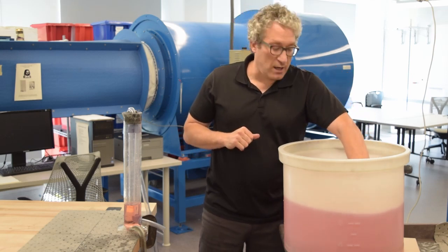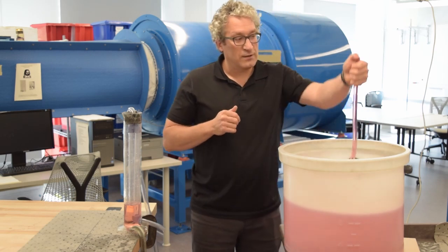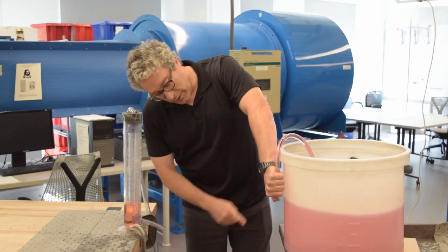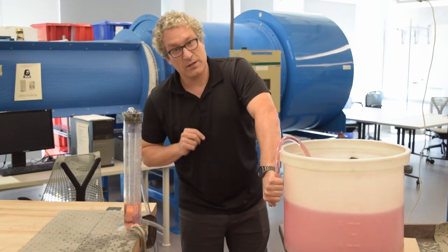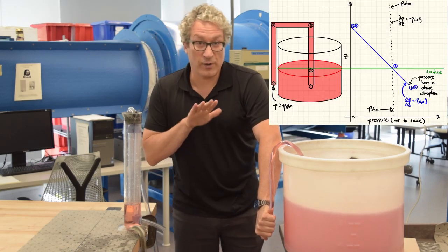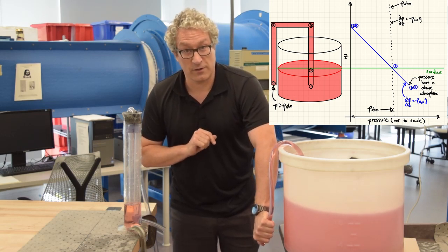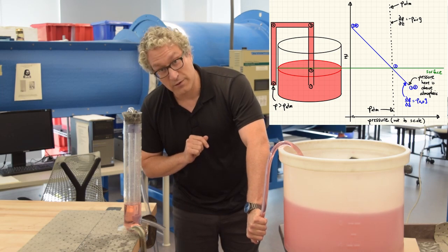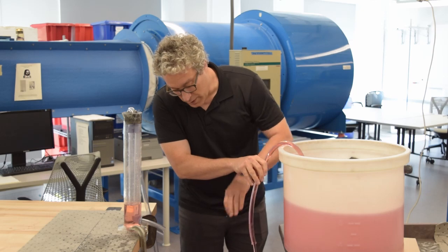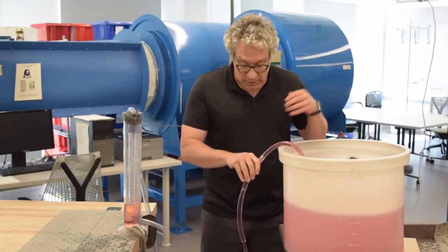But I can do the same math, and I can see what the hydrostatic equation tells me. And what it tells me is that if I hold it like this, the pressure here is lower. If I move it down and down, if I move the surface of this right even with the top, then I expect this pressure to be atmospheric. But as soon as I move this system down lower, now it has a lower z value, which means that the pressure of the fluid must be higher than that of atmospheric. And that means that when I remove my thumb, the water is going to come out. And this tube in this configuration, all it's doing is creating a connection from the reservoir to the exhaust.